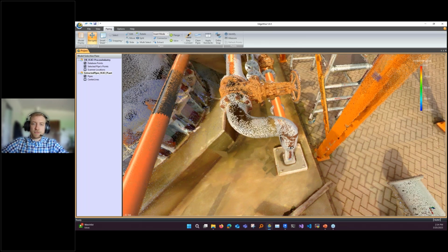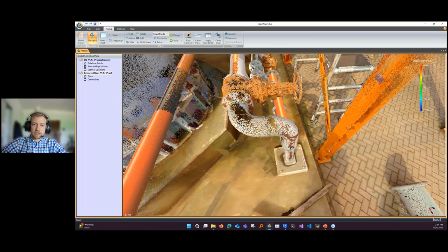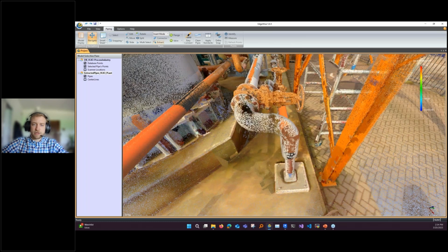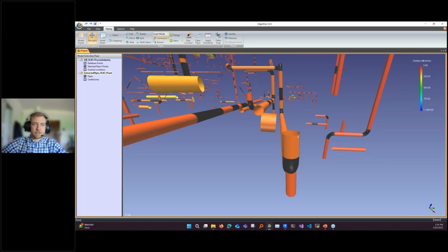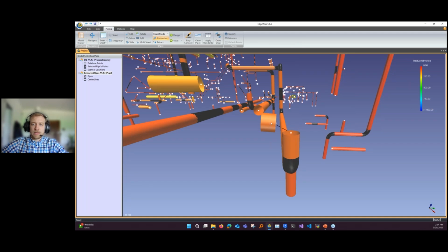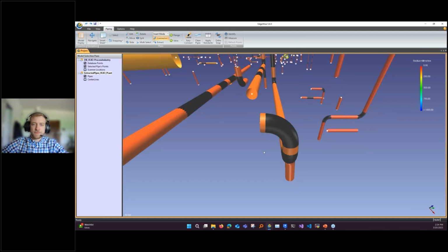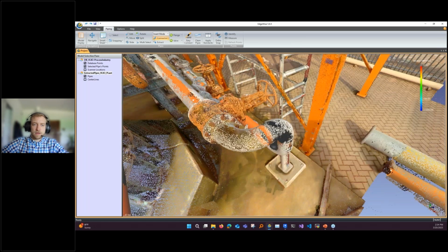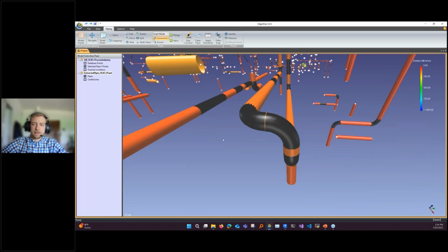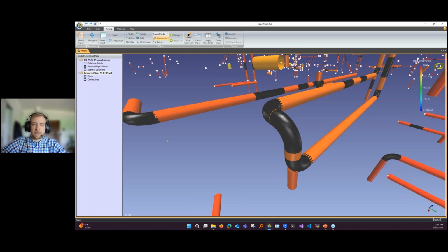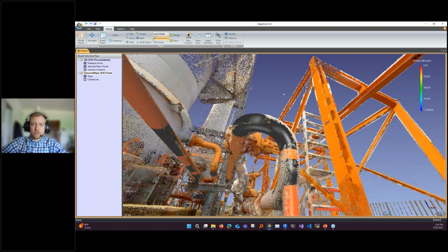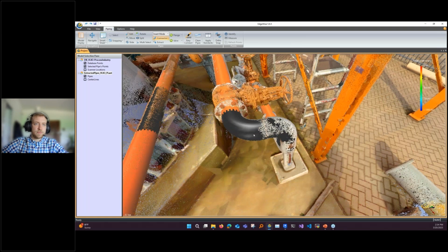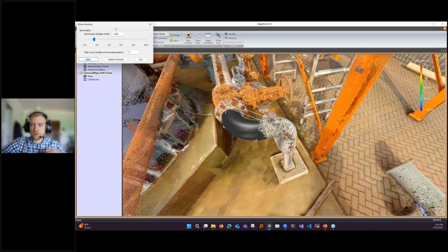The way that we hope to model this is we want to draw a box and draw a little sliver extraction, and we'll get that one set. We have our connect tool, and again, I'm going to use hotkeys a lot, but the connect tool is the C key on the keyboard, and that will create our elbow there, which looks reasonable. We can create our elbow here, and that's going to fill on that side, and that looks pretty good, right? That's not bad. There is the option to modify the elbow bend radius, and that can be useful for a couple of things.